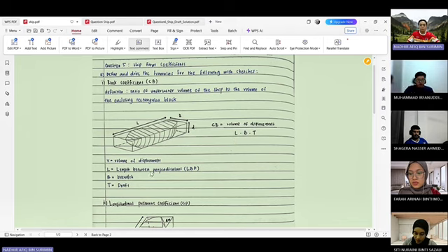You sum all the moments and get 2581 tons meter. Next is the initial moment, the displacement multiplied by the initial KG, and the answer is 45000 tons meter.